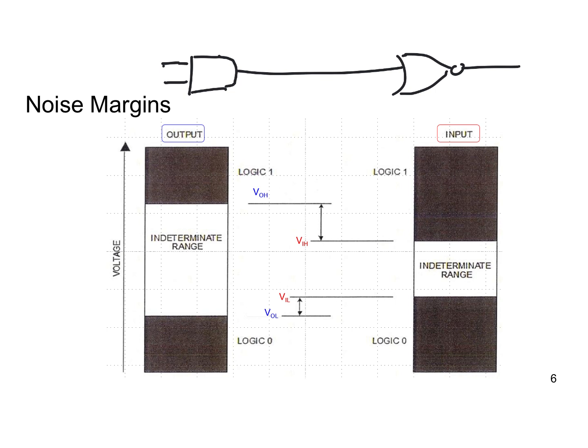VOH is 2.7 volts. Okay, and of course it can wander up to the 5-volt power supply for the output. That's the gate output for logic 1. For logic low, this can range obviously from 0 to 0.5 volts. Okay, that's because of the internal transistors.